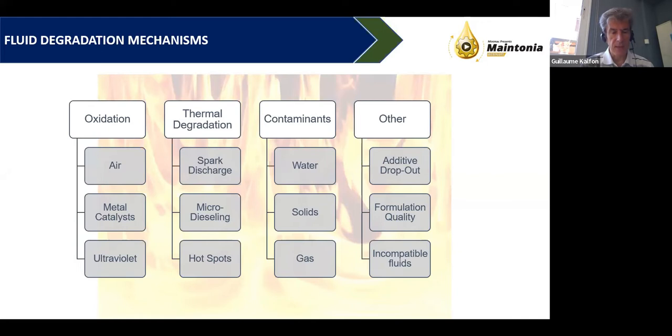will promote its degradation. And also, when we're talking about compressors, we are compressing a gas, and in many types of compressors, there are ways that this gas can ingress into the lubricating oil. It depends on the gas we are compressing. If we are compressing natural gas, butane, propane, all hydrocarbons, if they get into the oil, they will accelerate the degradation. It is true also of air, it is true of CO2, of carbon monoxide, even nitrogen.